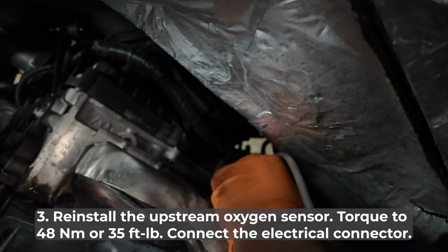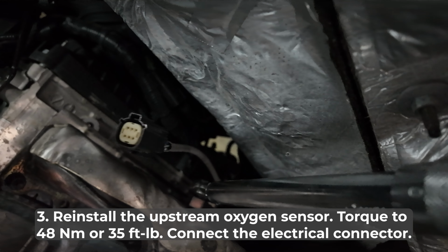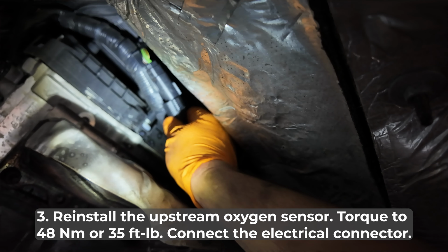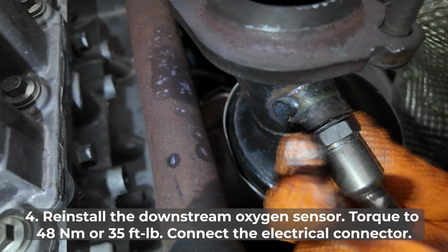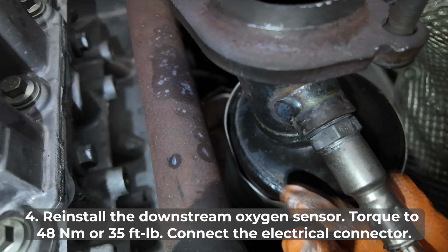Install the upstream oxygen sensor and connect the electrical connectors. Install the downstream oxygen sensor and connect the electrical connector.